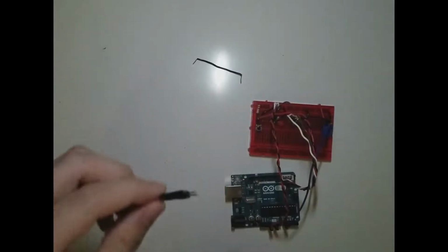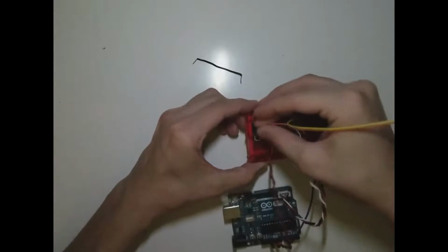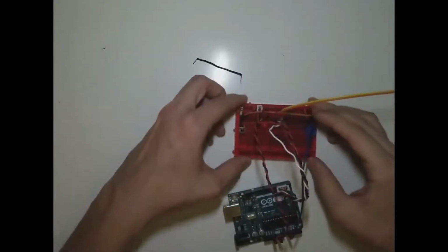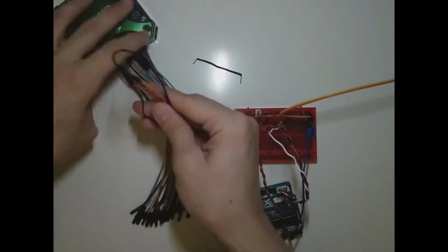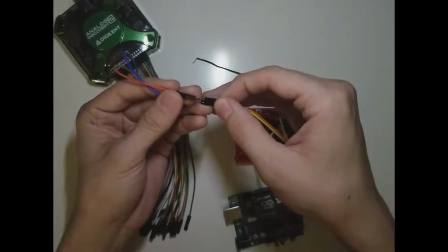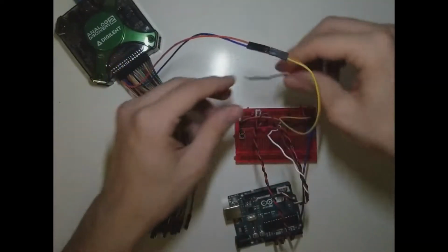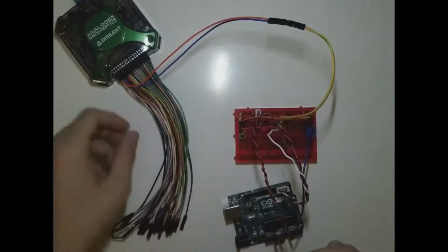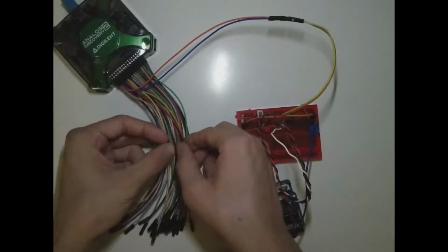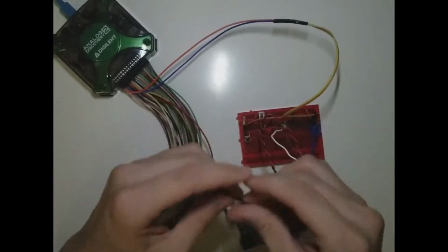And we have a couple extra wires to connect to our oscilloscope. Just for neatness, I have the negative terminals for channel 1 and channel 2 connected directly to ground. And I'll connect one of the other ground pins to the Arduino ground. Ground is basically your reference point.